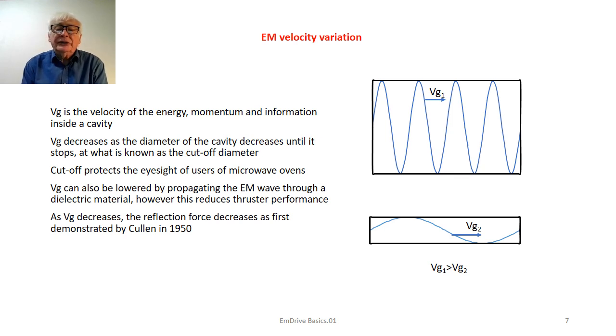Now you can see the effect on guide wavelength if you look at the diagram, which shows a large diameter cavity and a small diameter cavity. You can see that the guide wavelength for Vg1 in the large diameter cavity is much smaller than the guide wavelength for Vg2 in the smaller cavity.